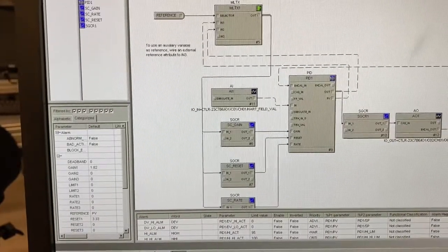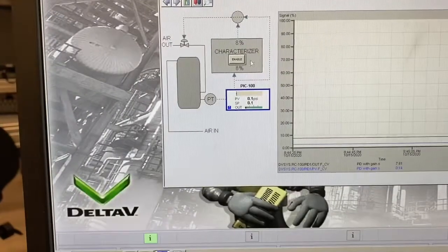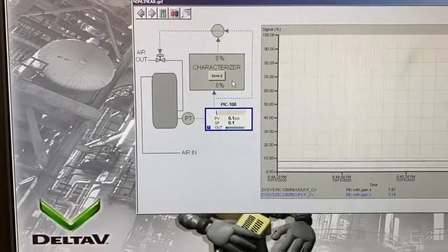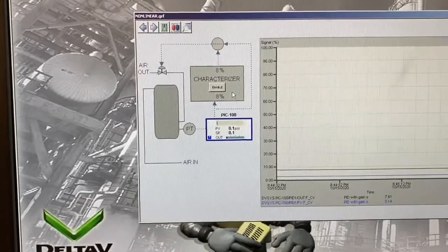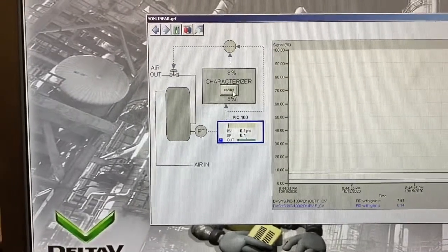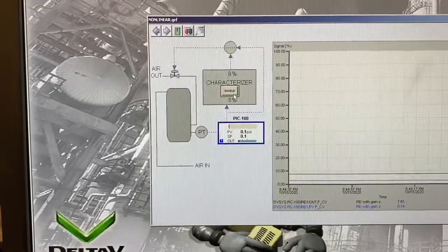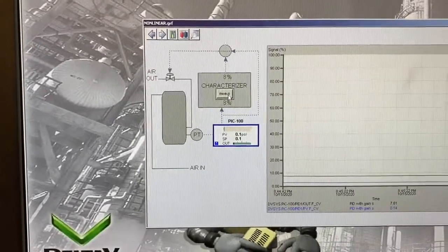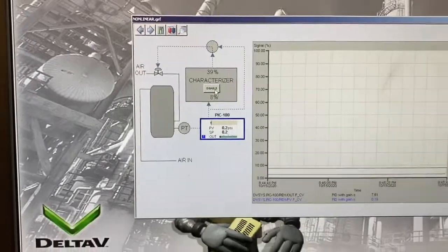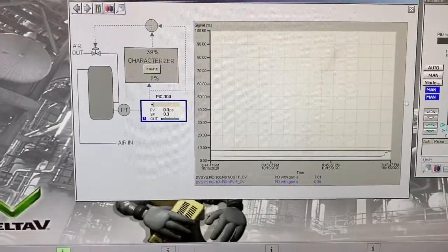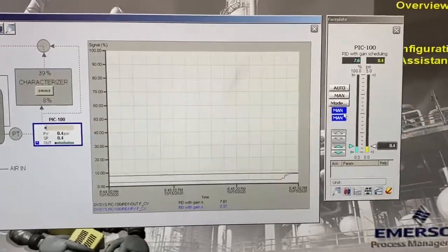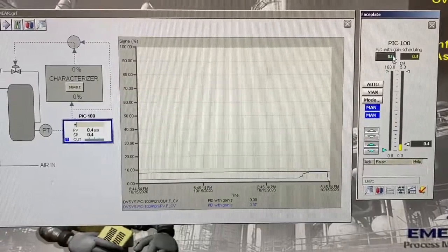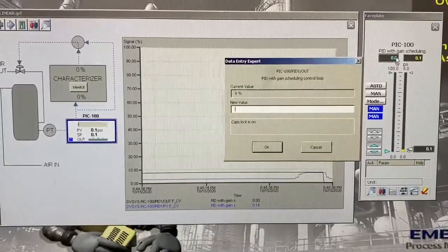So this is set up, and I can enable and disable it. If I go back over here, that's where I wanted to show you where I'd be entering all those values that we got from our graph that I plotted in Excel. I've entered them already, the correct ones in the correct XY array, or table basically. And if I click enable now, I want to show you what this does. So it's enabled. We're in manual mode right now, and let's put our controller output to 0. We'll start at 0. We'll go to 5%.